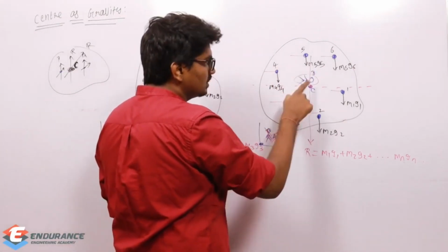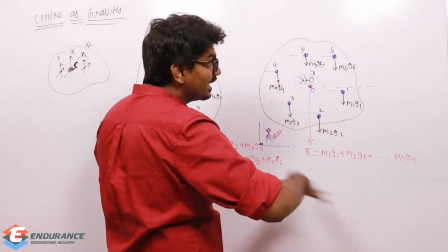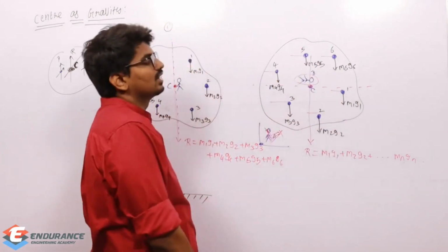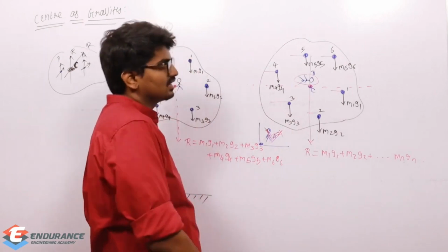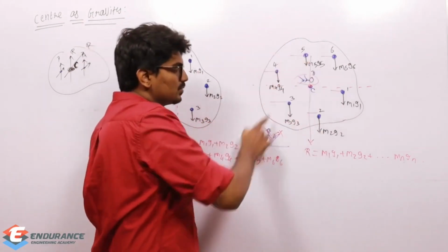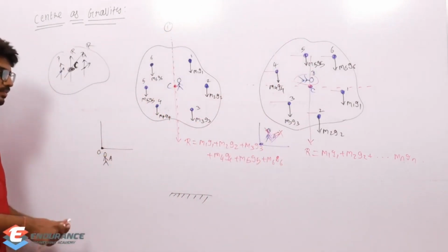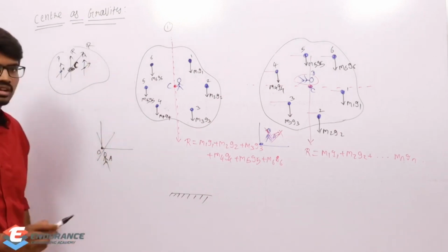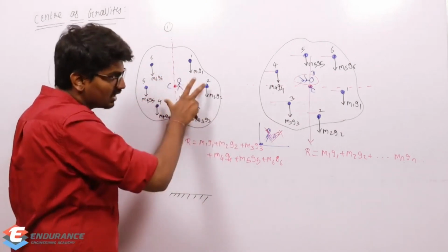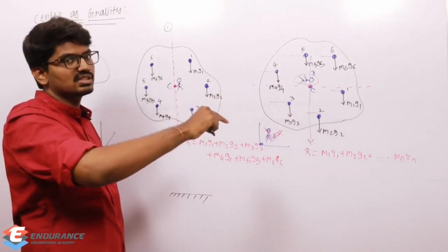So the point through which the resultant passes, irrespective of the orientation of the forces which are due to gravitational effect, with respect to the same body. I am not measuring with respect to some other point. With respect to the same body, the position of masses has not changed, but if I rotate it, only the orientation of the gravitational forces is changing.